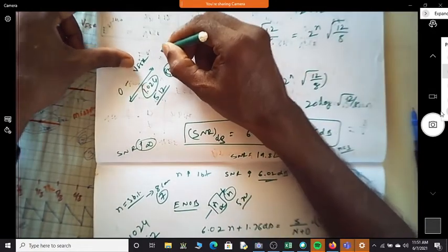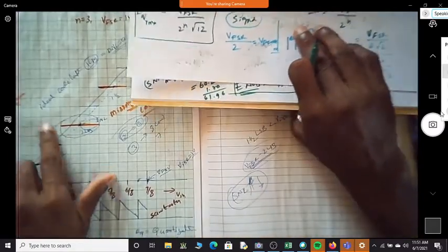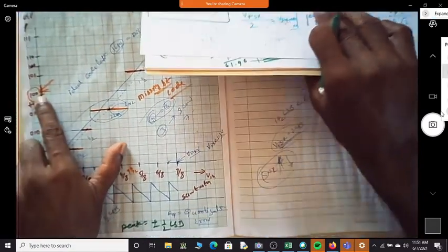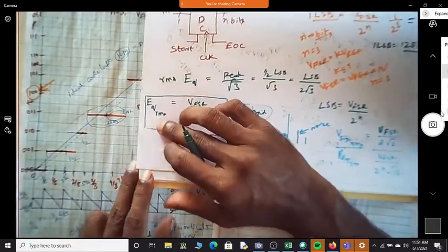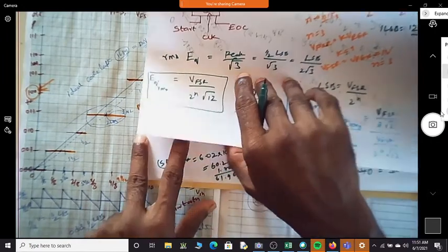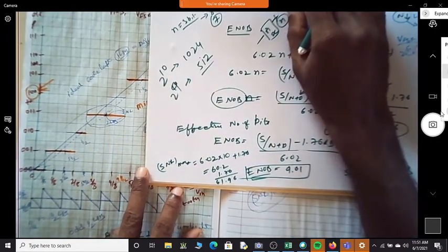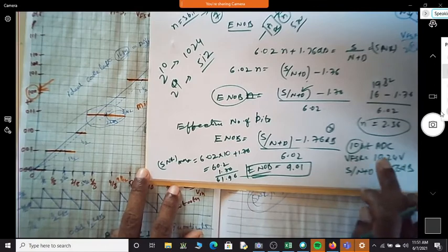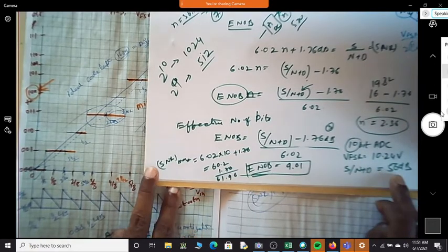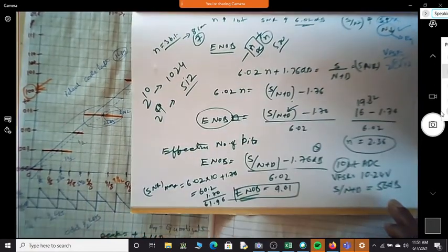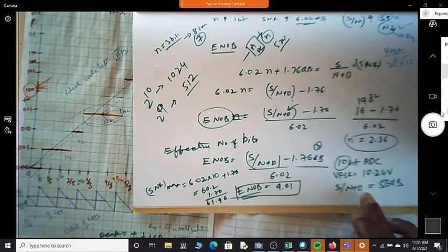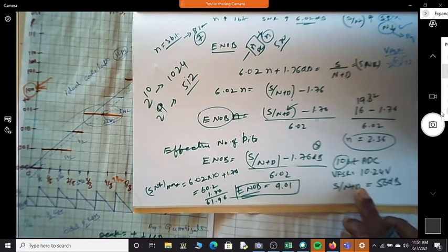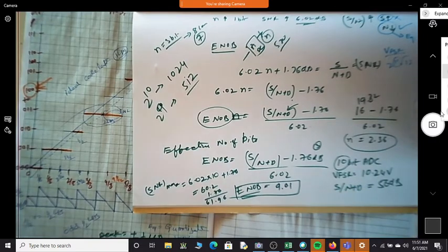Likewise, for this 10-bit ADC, you may lose half of the representation because of the error with a signal to noise ratio of 56 dB. So the intention here is we should have ENOB close to the value of n. That is possible only when you reduce the distortion. Only when you reduce the distortion.